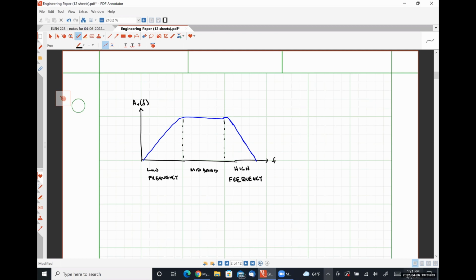So that's why we start losing gain to stuff like R pi is shorted and R naught is shorted. They start going from looking like an open circuit in parallel with it to having some finite impedance, to eventually looking like a short directly in parallel with it. You're 100% right. So we are talking specifically about this area because it's the only one that we don't really know anything about. Because these capacitors we choose, we have control over them because we physically place them in the circuit.